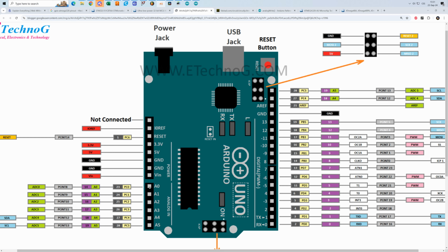And all of these pins have an ADC, meaning that they can process analog voltage, they can input analog voltage, but this chip doesn't have DAC. So that means it's not capable of outputting analog voltage. It doesn't have DAC at all. We've seen before with the STM32 chip that it also just had two DAC channels. This one doesn't have any. So it cannot output analog voltage.